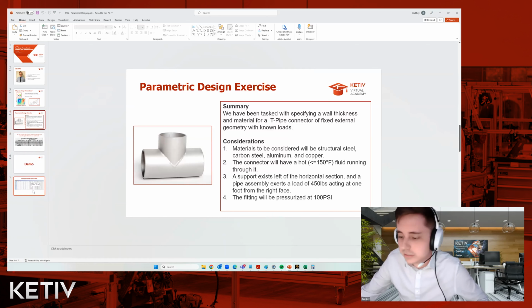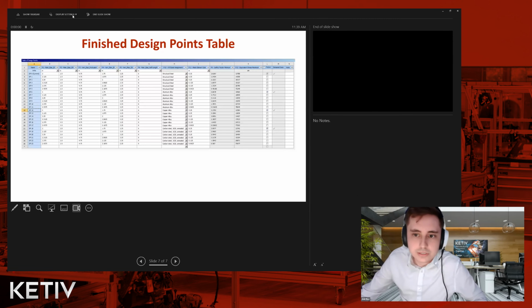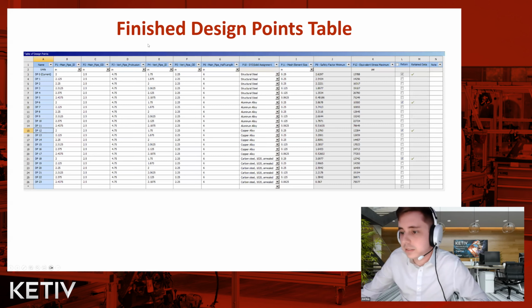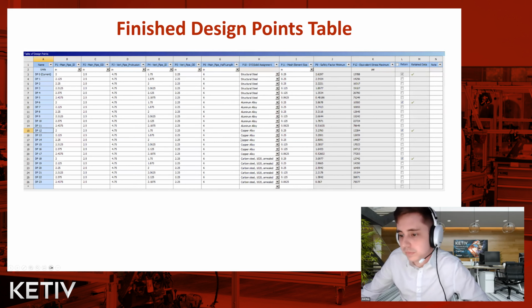So if I go to this finished list of design points, let me swap views here. We can go to our safety factor column, and right, we don't have a price column, but we know that our aluminum alloy is the cheapest, right? So the thinnest aluminum alloy fails, right? So is there maybe a thinner other component that passes?